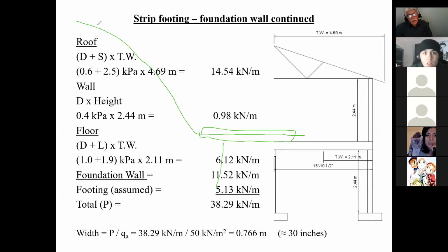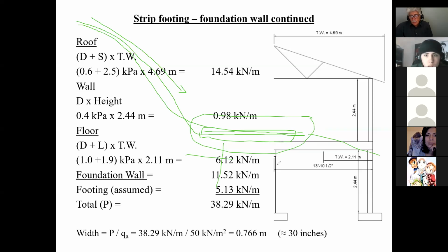So what I did is I calculated here a very rapid flow so that all the fines would not settle here. And then I changed the slope here so that all the fines would fall out here. And therefore, this is the only part of the ditch that had to be maintained. It was very convenient because it was right beside the road. And I did all that calculation based on those flow equations. So was I happy? And then when I went to see the result, everybody was so happy.